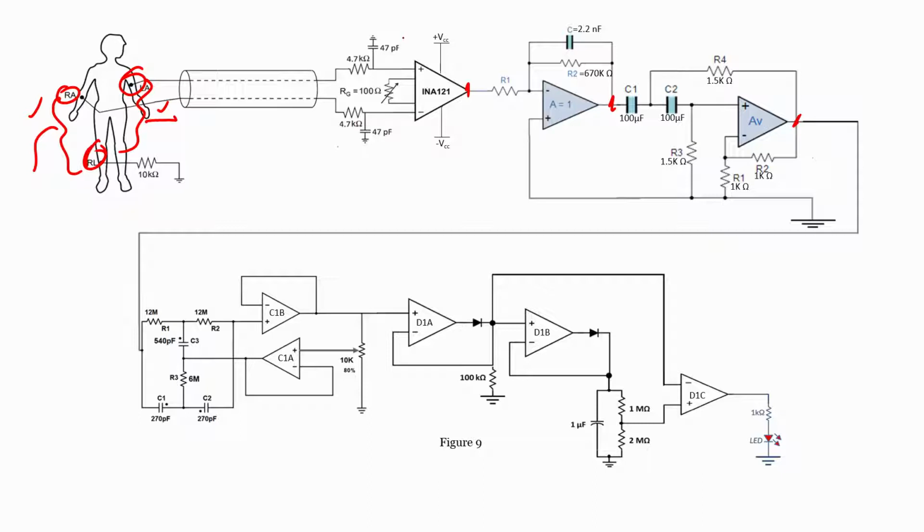So that is the reason we will be going with an instrumentation amplifier, and the one that I am using here is INA128. You can look into the data sheet to understand the detailed architecture and specifications of the INA128, so that you will also understand the working, the gain setting, the resistance value that we choose and why we have chosen it. Now when we see the output at this particular point, since it is not a processed signal and we have only done the amplification stage, we can see the raw ECG signal, an amplified version of the ECG signal.